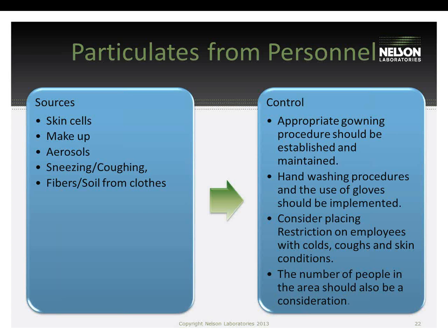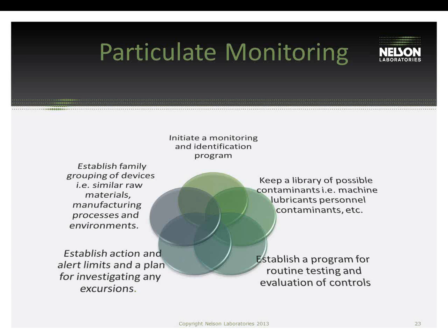Also, the number of people in the area may be a consideration. Increasing the number of personnel doesn't just increase the amount of particulate matter that's shed, but also increases the amount of turbulence in the air, those types of things. So keeping that to a minimum is important if possible.